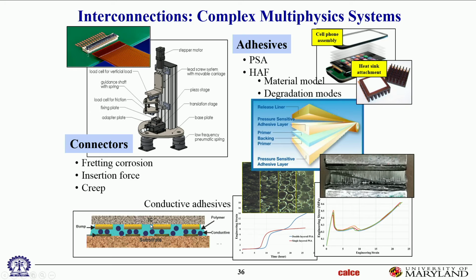And again, there's a lot of work we do on those kinds of polymers. Reliability of those polymers is a big problem. They delaminate, moisture gets into them and changes their properties. There are all kinds of issues that happen. They slowly lose compression force, because you need compression force to have the right contact resistance. You lose that compression force, the contact resistance becomes too high. So all of those are degradation mechanisms in conductive adhesives. Again, there are bodies of researchers, including my group, that do a lot of work on that. Other kinds of adhesives are not electrical, they are just performing a mechanical function.